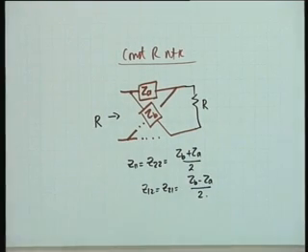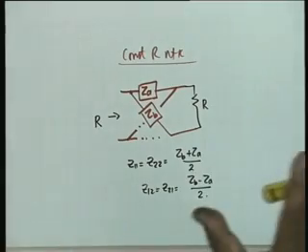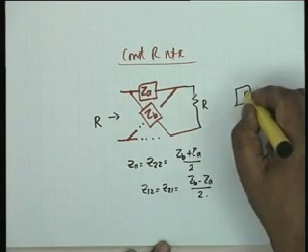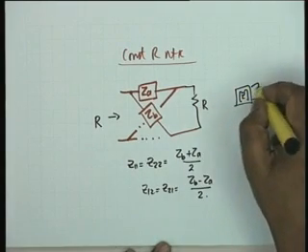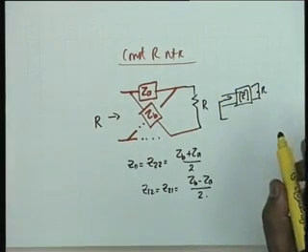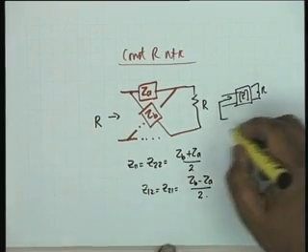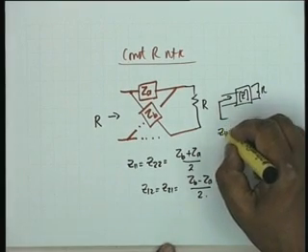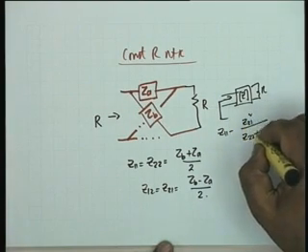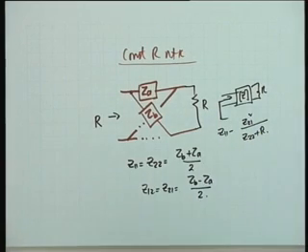All right. Now you also know that, well, you recall that this is a folded version of a bridge network that we demonstrated yesterday. Okay. Anyway, you also know that if a 2-port is terminated in the resistance R, can you find out the input impedance in terms of the Z parameters? The input impedance is, we have shown this earlier, it is Z11 minus Z21 squared divided by Z22 plus R. This is the input impedance. Can you prove this?